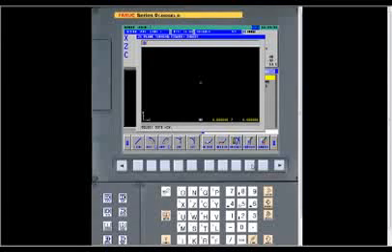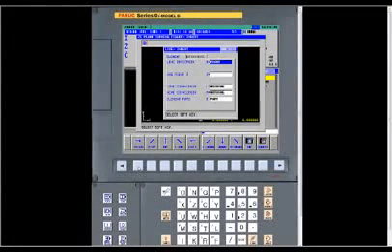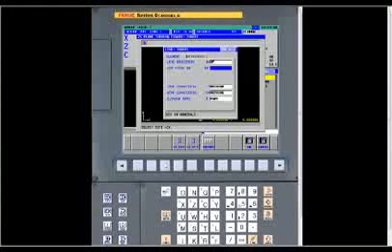So the first one we have to do is we know at the end of this part there's a flat on the end of this ball. So we need to do a line up that first diameter. And see, it gives you all these different directions for where we're describing what we're doing. And we're starting at 0, so we're going to go up. And the finished dimension is 0.9312.